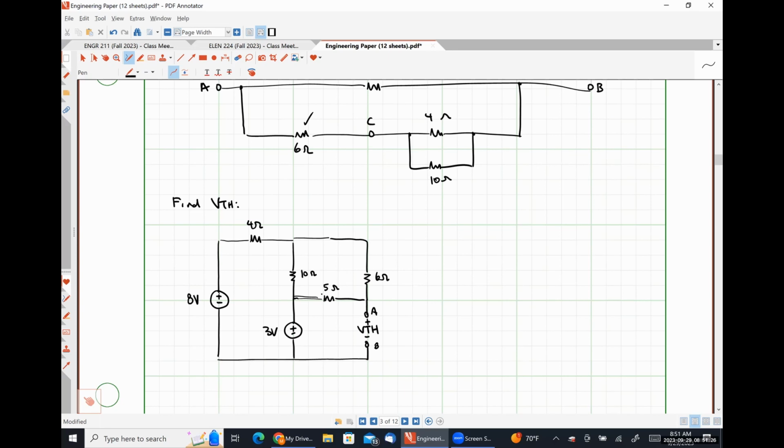And the middlemost node would have a voltage of 3 volts, which means I only have 2 unknown voltages left in my circuit. So I have a 2 equation, 2 unknown system using nodal, or a 2 equation, 2 unknown system using mesh. Since we're trying to find a voltage, nodal gives us voltages, so we don't have to do any additional post-processing to our results like we would have to do with mesh. So I would argue that nodal is the better choice for this particular circuit.